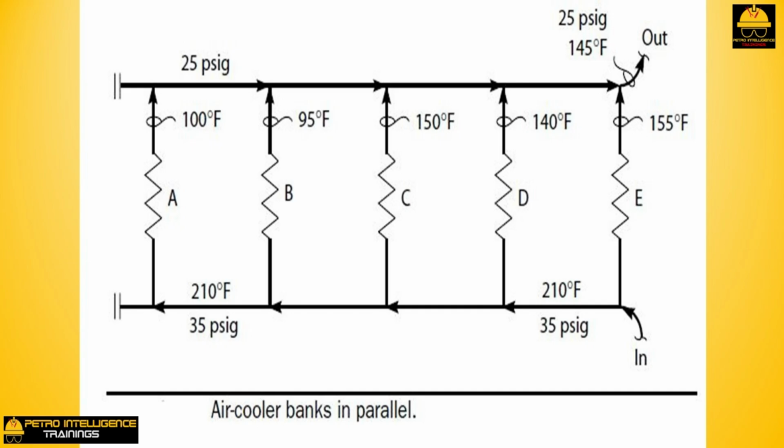Why would the flow through A and B be so low? Apparently, their tubes must be partly plugged. Corrosion products, gums, and dust are common plugging agents. But when such exchangers foul, their relative tube side delta P, as compared to the other exchangers, remains constant. But their relative tube side flow, as compared to the other parallel exchangers, decreases.